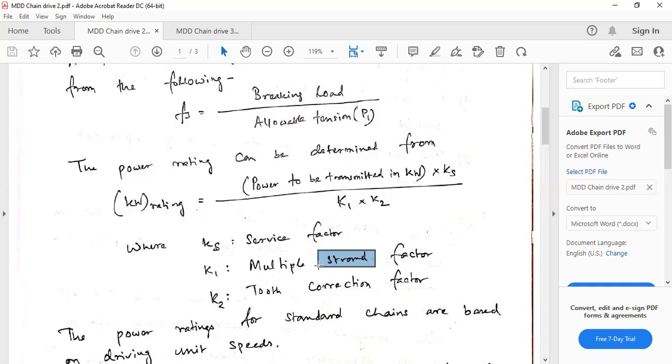If you connect two chains together, I have shown you an image of that, we extend the rollers and connect more links to give it the shape of two chains connected together, and they transmit the torque together as a whole. That is a duplex chain. Similarly for three. So more than one strand is multiple strand.